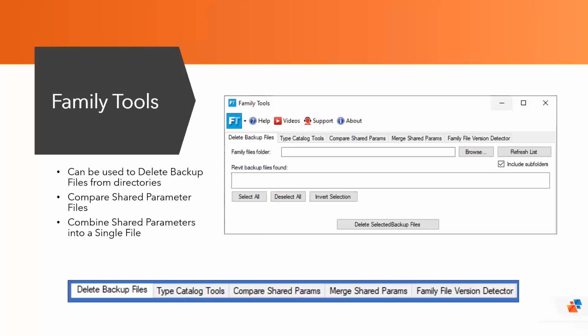So the type catalog tool is quite an interesting one. If you're ever doing anything with type catalogs, that means that you're probably deep inside Notepad, and inside of there, you're having to put all this information in, comma delimited text files, and it's really not very user friendly. So what the type catalog tool enables you to do is actually manage that information inside of an Excel file, and then you can take a CSV file and convert it into a text file. So it means you can do some of the cool stuff that Excel gives you the option to do, like naming things based on the parameters of the family inside of Excel, and then export it out as a type catalog. All right, so quite a powerful little tool there.